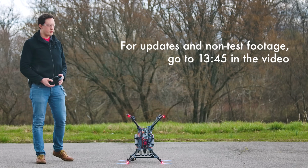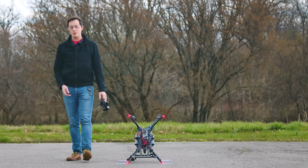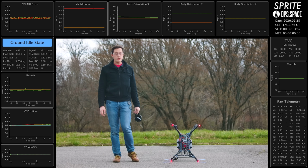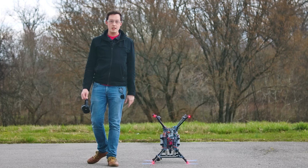All right, hey folks, we're out here with Sprite again, doing some more hop tests. We're going to 1 meter for about a minute. The minute is determined based on the mission elapsed timer, which you will see in the top right of your screen. That's the MET colon piece of data there, and once it hits 60, you'll see Sprite shift into the descent stage. We're gonna try to hover at 1 meter without translating, moving, having any speed in any direction.